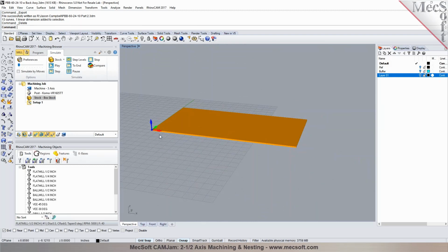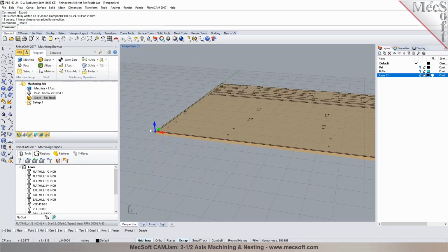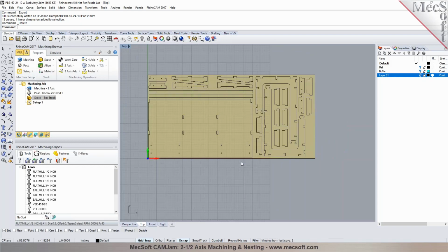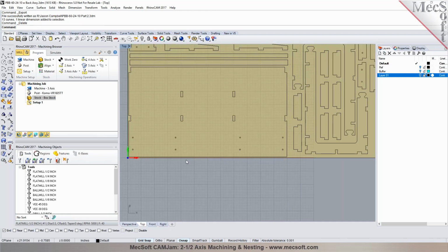And you can specify where you want to put your XYZ origin, which could be your work offset, your G54 or G55. And currently it is where the origin is in the CAD, since you already have the part drawn at the origin. Would you like to specify a different origin for this part? Not at this time. The way we've been running it with our other milling package is we lay the parts out like this with pre-arranged buffers, and then do the boring or drills, and then internal cuts, and then perimeters.